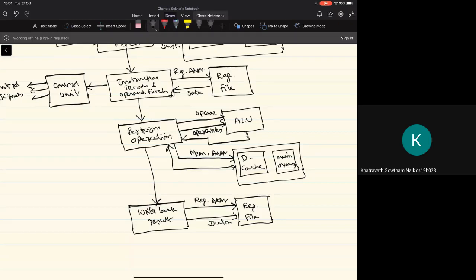What we have seen is that typical arithmetic operations may take of the order of a few tenths of tau. We have seen that an integer addition operation may take about 15 tau or 20 tau. The multiplication operation may take about 40 tau and so on. Now it depends on what the value of tau is. Tau will typically be a few tenths of picoseconds.